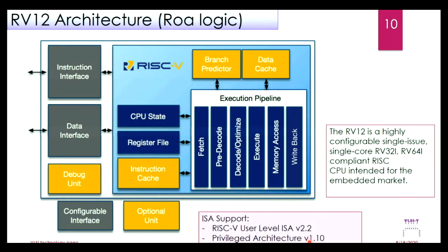For our VG SoC, the configurable interface will be changed, because the original core only supports an AXI-lite interface. So we add more interfaces to this configurable interface. Currently, the SoC can support the AXI4 protocol.